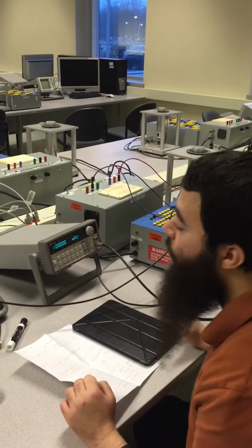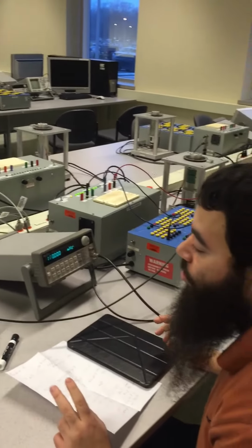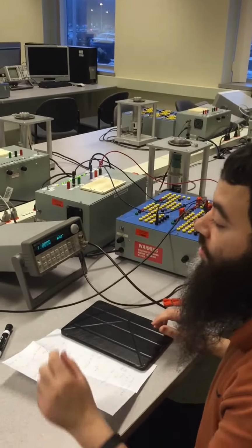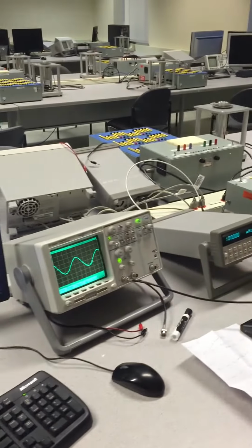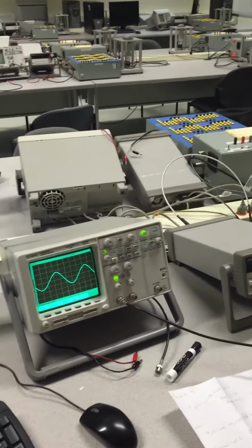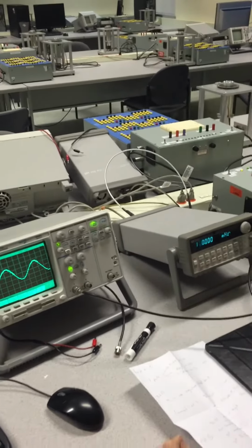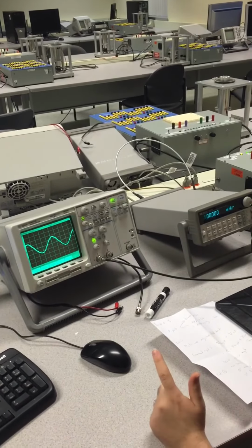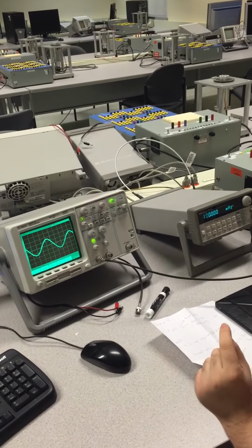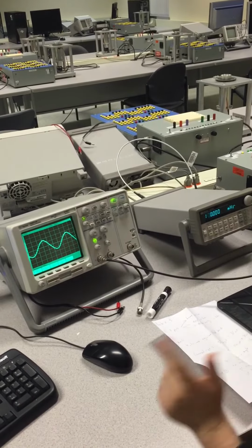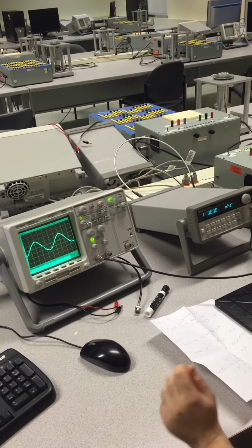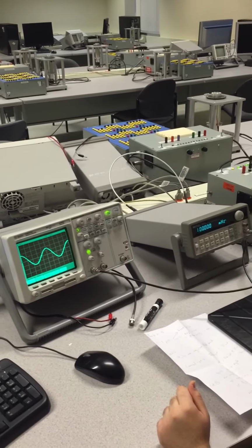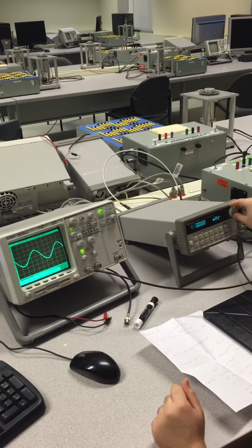Now let's increase the frequency. Two things will happen. First of all, the non-linearity will decrease. Second of all, the amplitude of the signal depends on the frequency here. You will need to record the value of the maximum frequency and the value of the maximum amplitude. If you have both values, you can calculate the constants A and tau m for your motor. So let's start to increase the frequency.